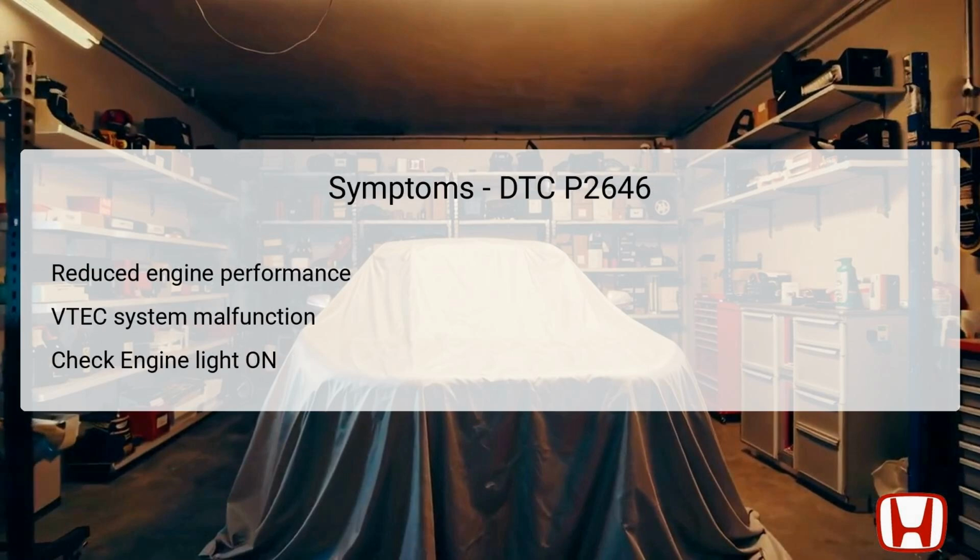Recognizing the symptoms related to DTC P2646 is crucial for diagnosing the problem effectively. One noticeable symptom is a reduction in engine performance, particularly during acceleration, which may be due to the VTEC system not engaging correctly. Drivers may experience a lack of responsiveness from the engine, leading to a less enjoyable driving experience.